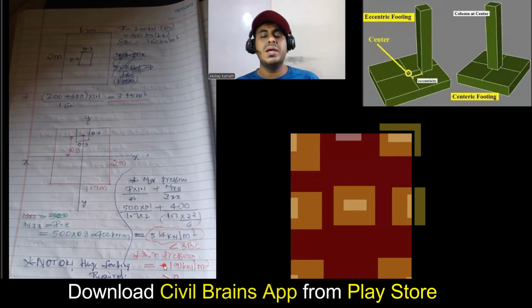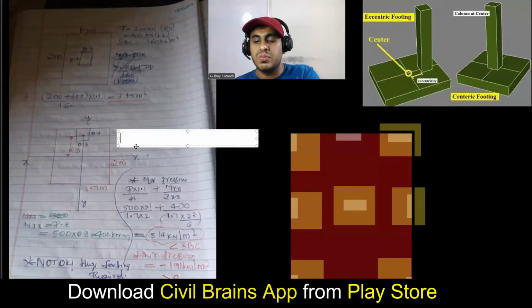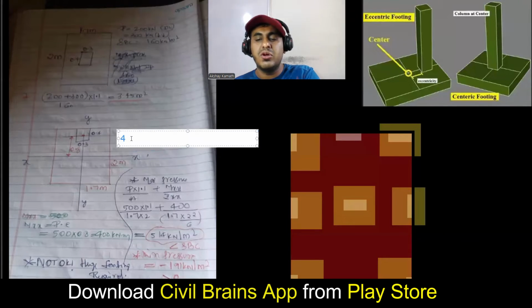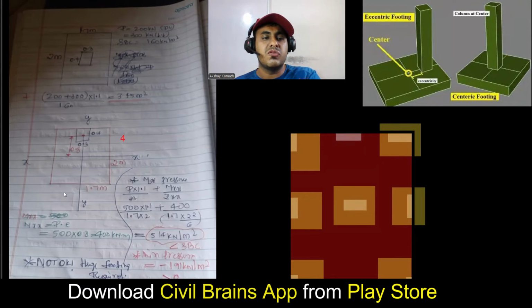Now you'll say, sir, why is there so much problem? You just increase the size of the footing, no? We'll increase. My size was 2 meter by 1.7 meter. I'll take a size of 4 meter by 4 meter. So you may say, sir, why are you worrying so much? You just increase the size, no? If you increase the size, obviously it will pass. We'll do that. I'll take a footing size of 4 meter by 4 meter. Okay. Do the calculation and tell me.